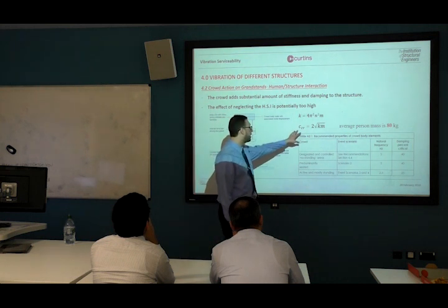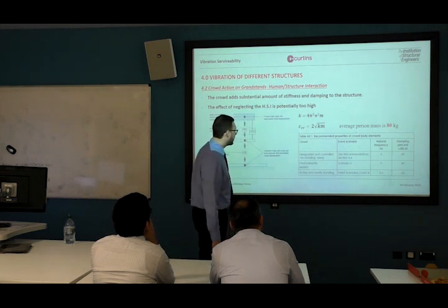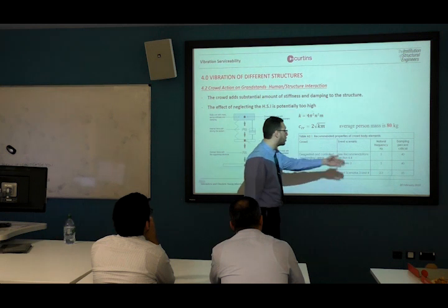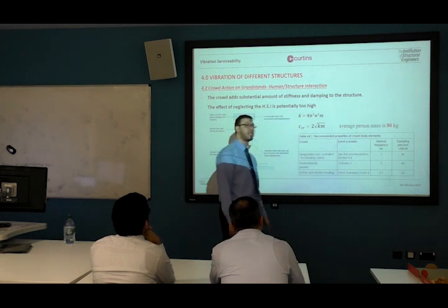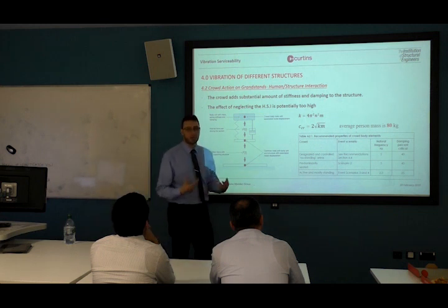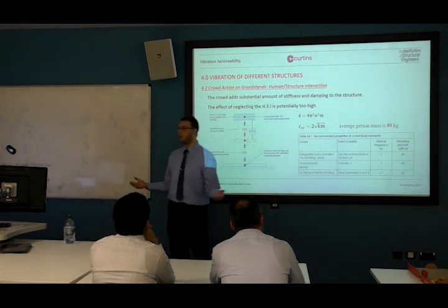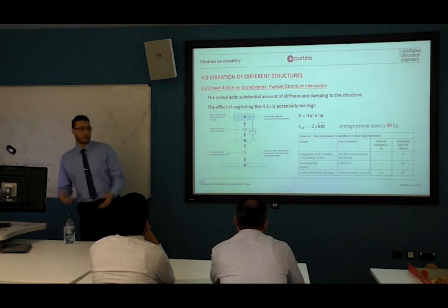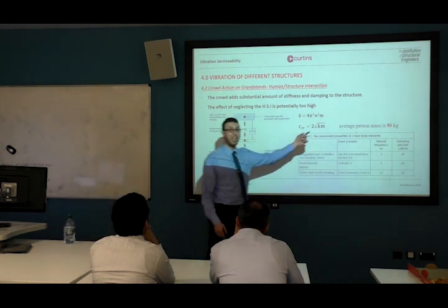And the way we calculate the damping is as a percentage of the critical damping. The critical damping is 2 square root of km. Now m is my weight, or the average weight of any sport fan, which suggests here it's 80 kilograms.